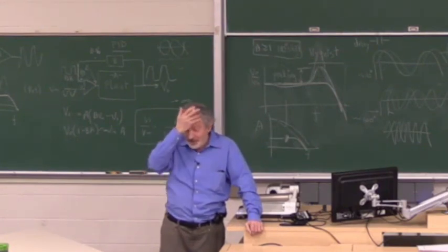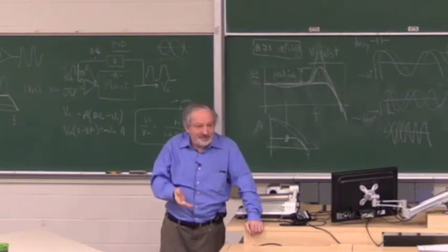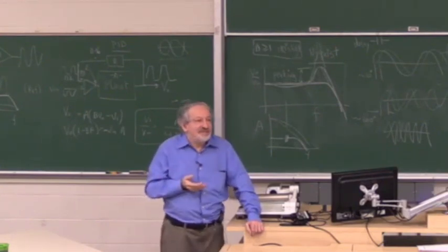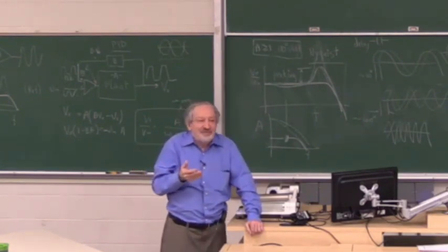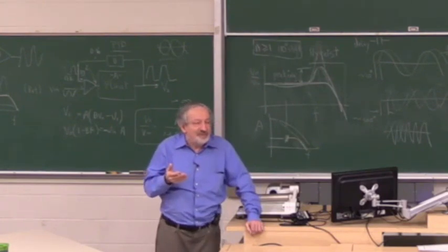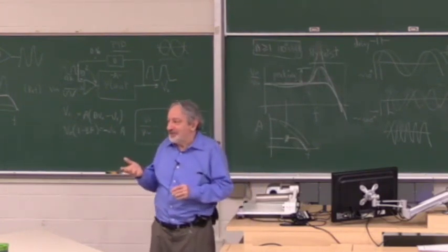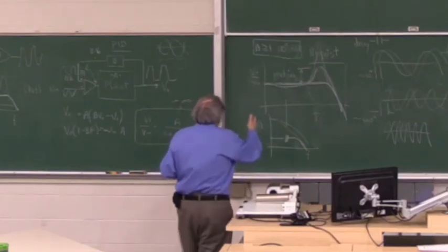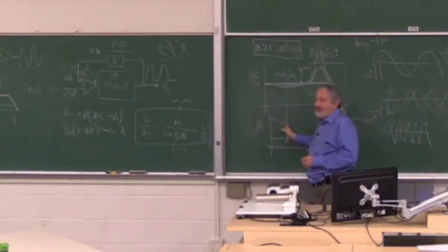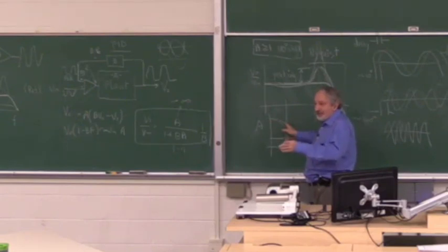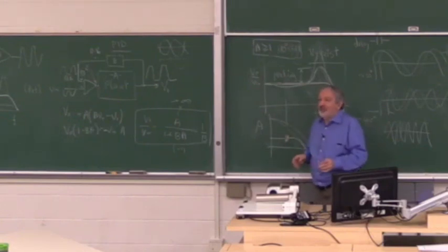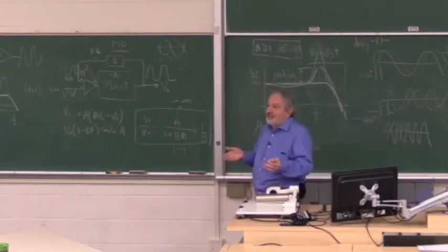If you look at the differential equation of a second order system and you draw amplitude and phase, any resonance implies a phase shift. It could be much higher than that, but at least to be a second order system, the phase changes 180 degrees. But this whole servo doesn't work if the phase changes 180 degrees. As a matter of fact, by that point, there may already be a phase shift, even without the resonance. So it doesn't even have to change 180 degrees. It only has to change by enough that the natural phase shift plus the resonance will push it 180 degrees. But the resonance alone will push the phase shift 180 degrees just by the second order equation.